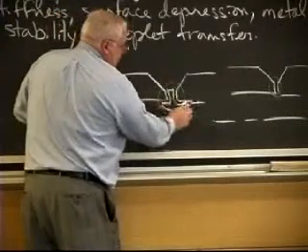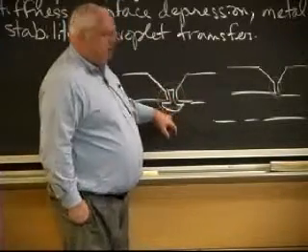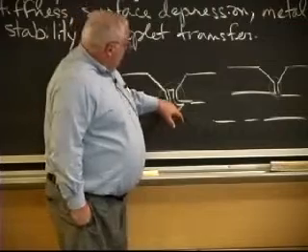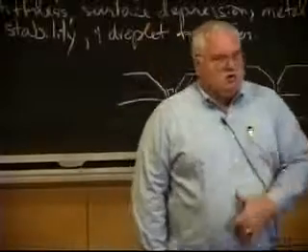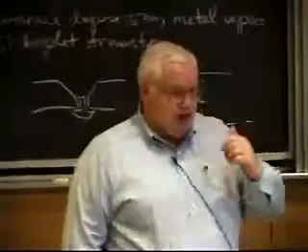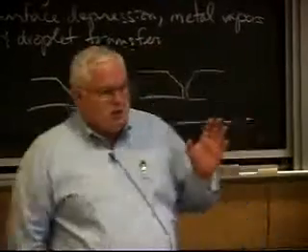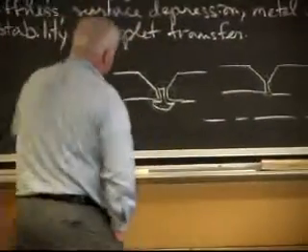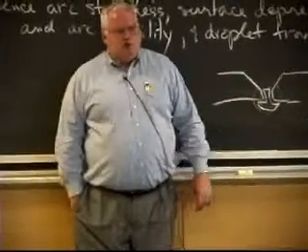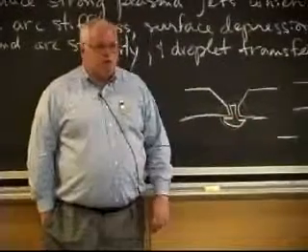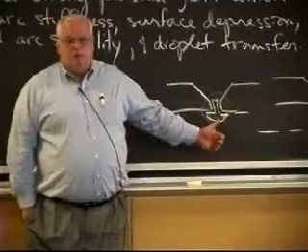Hopefully, if you do it right, you'll get a beautiful bottom root fusion with gas tungsten arc, non-consumable, for the root pass. The wire is rolled to that shape in cross section, so it's not actually a nail. The problem is that it's expensive, and each of those little rings costs extra. It's actually not that expensive, only a couple bucks. But it's really only high quality welding, such as submarine construction piping, that people worry about that.